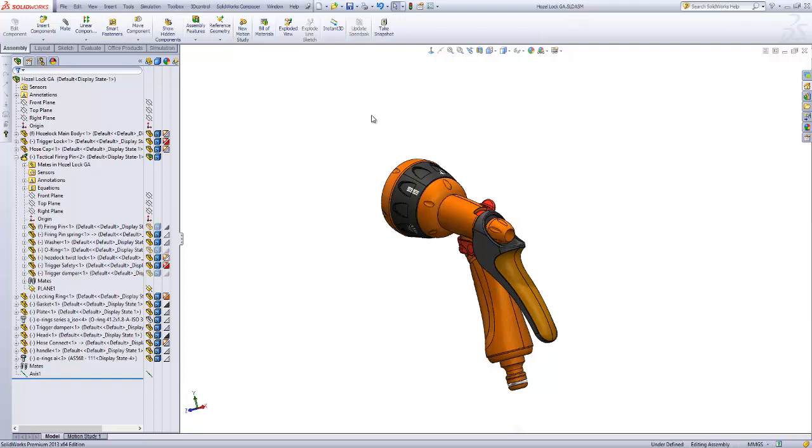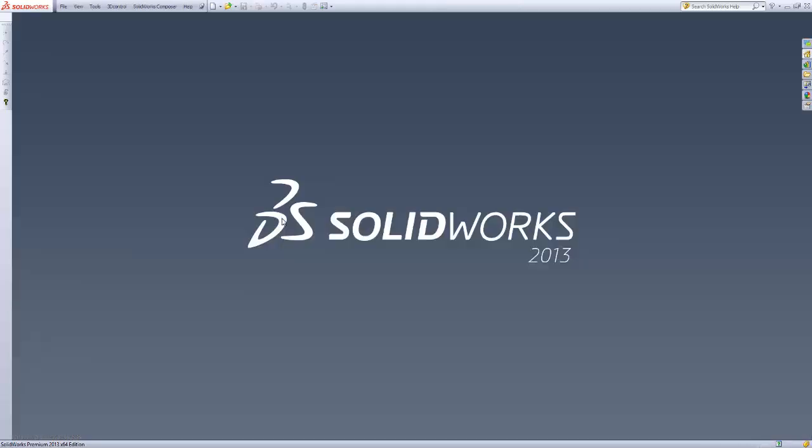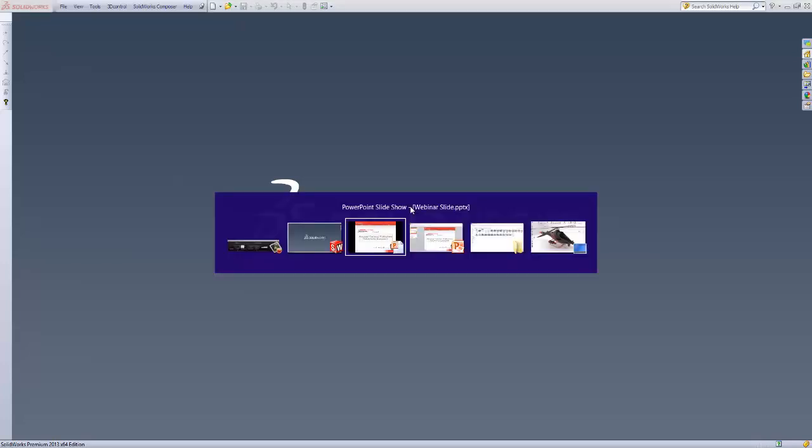So those of you that are familiar with importing files such as STEP or IGES, especially assembly STEP or IGES files, you may note that they'll come into the assembly and then all the different parts will be displayed in the tree, similar to this, but there are no mates that come in or anything like that. SolidWorks Composer is very similar to that. No mates are maintained when it brings in. It's almost like geometry floating in space. So what I'm going to do is just close this, and let's go and load Composer now.